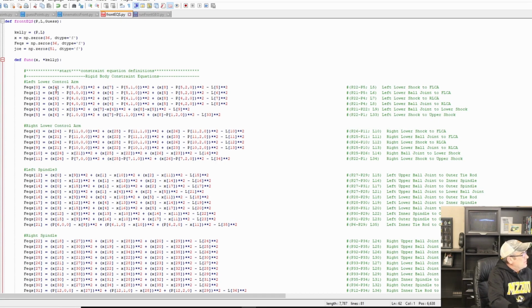In this equation, that's where I've introduced some known points. So I kind of bypassed the joint constraints, but I just wanted to be clear that in reality, outside of this application, if you were doing multibody dynamics, you would actually define the bodies and then define the joint constraints. And I just wanted to point out that I bypassed that step when setting up those functions, the input function vector for our least squares function.